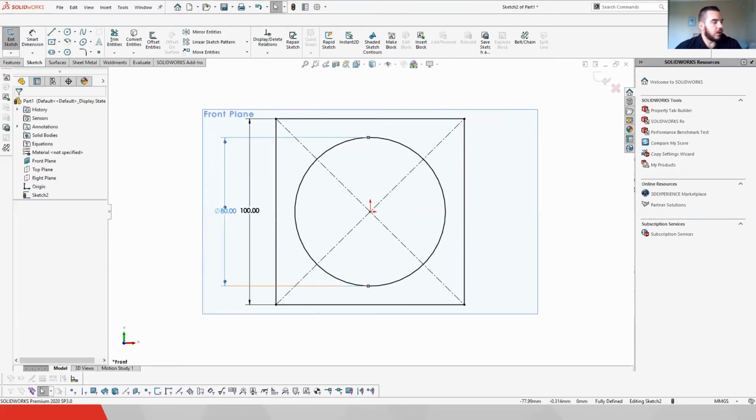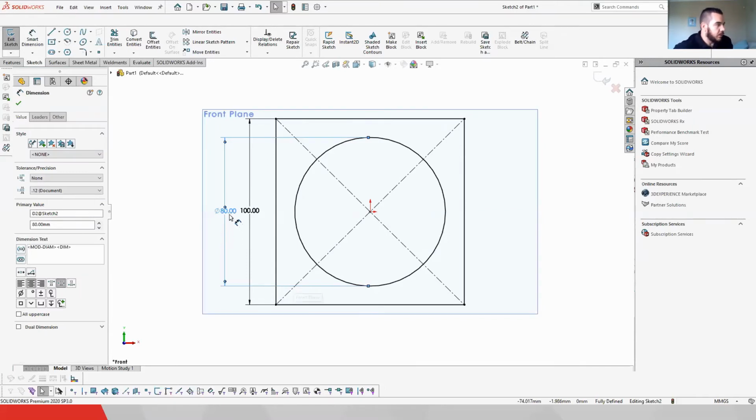If I decide, okay, now this is now my diameter, and I rather want to go and change this, you can click on that dimension, and you have here on your left-hand side, first of all, all of your tolerancing types, minimum, maximum, if that's applicable in your industry. And you can also go and change the precision. So the precision is just basically how close to that specific zero should I get. Most of the time we accept a 2 decimal or a 3 decimal. Okay.